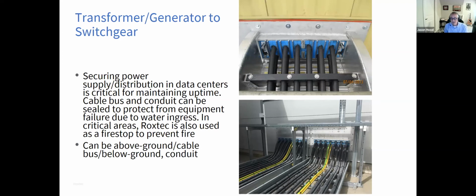And again, I'm talking a lot about preventing water infiltration, but a lot of these applications also need to be fire rated. So when you choose a type of solution here for an exterior penetration, it's not only about water. A lot of times it's multiple demands. And that's very important when you're looking at what's to be used on the side of a building.